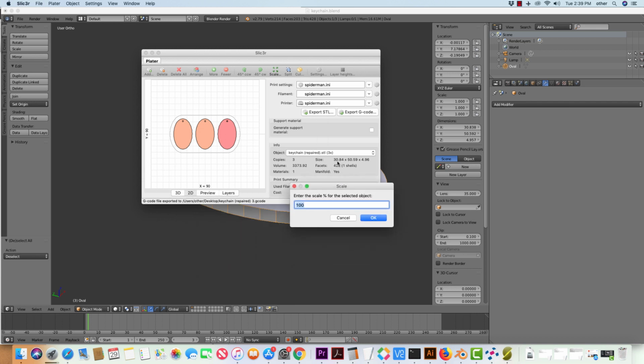If I wanted to say like 31 millimeters, what percentage would that be? All right, so Blender would be the preferred state for making things bigger and smaller. And then you would, of course, have to take it to NetFab, clean it up, then bring it back. So it's a pretty good grind of the workflow, but if you like 3D printing, hey, it's worth it. All right, so that is how you do that.